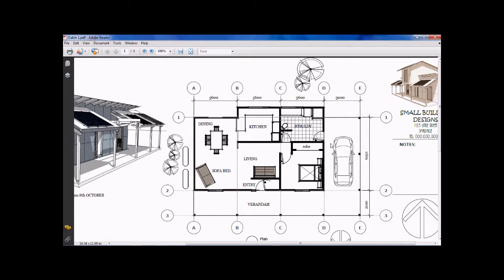The reasons for those dimensions are as I envisage using something like a sheet product for the facade across the front, which would come in normally 1.2 meter wide sheets. So that's why the multiple of 1.2 creates 3.6. We'll end up having no wastage on site, or we'll minimise the wastage on site, which is a very sustainable